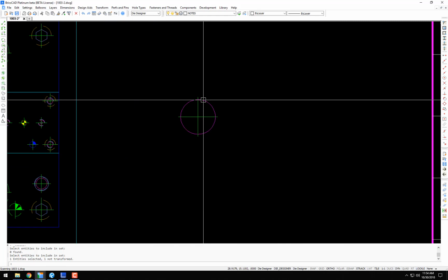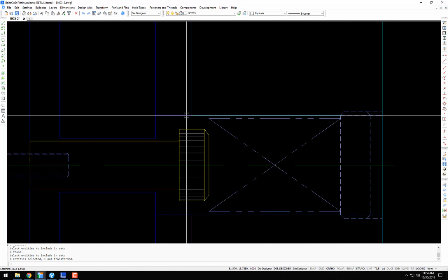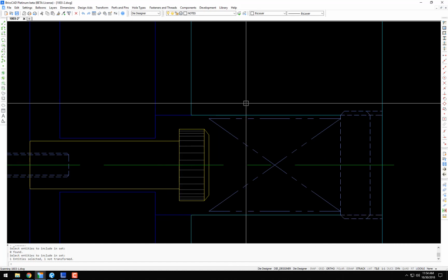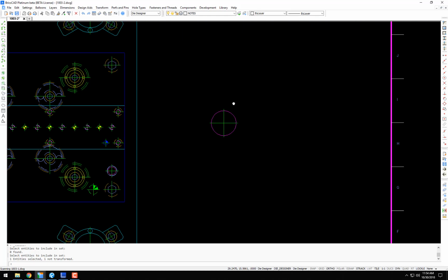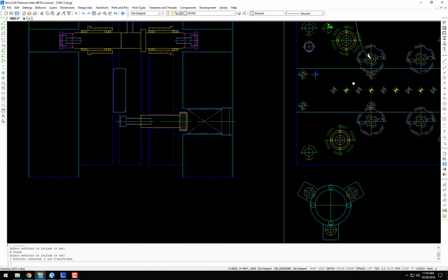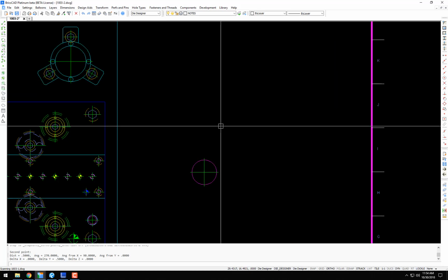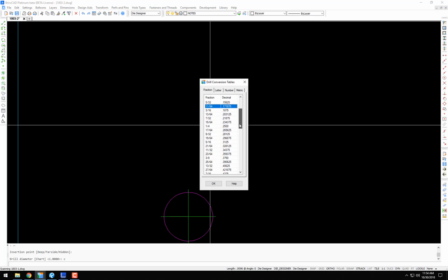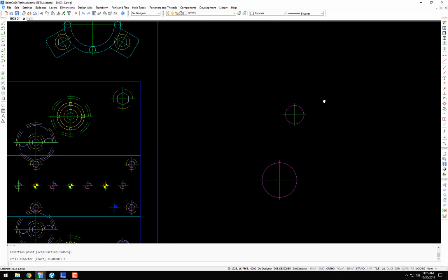Just to explain, that drilled hole in this case is only going through this backup plate. This is going to be a tapped hole, but if it doesn't transform into what you want, you can do a search and replace. So just for instance, this transfer pin is probably 1/2 inch. It is a 1/2 inch. So we'll start a drill. We'll go to our chart and we'll make it a 32nd over that 1/2 inch. Okay, so there's our drill, 32nd over.